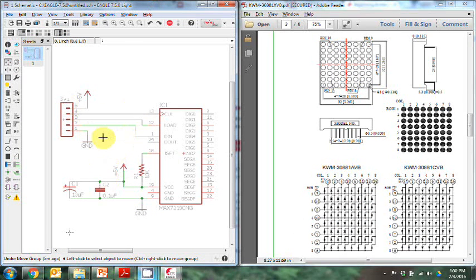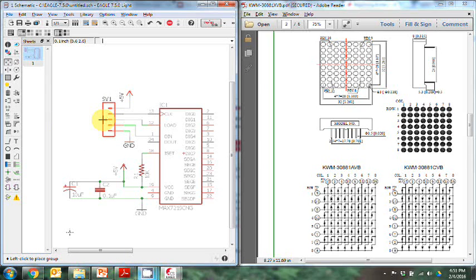So now that most of my schematic wiring is done, I want to do a little bit of cleanup, right? So what I'd really like to do is to move that header in a little bit. It's kind of sticking out. Now I can just move the component, but it doesn't move all the things connected to it. So I'm going to use the group tool to highlight a whole bunch of stuff. And you can see once I've selected it, the move tool is automatically selected. So I'm going to hold down Control, then right click, and I can move the whole group at once, which is really nice. So next we want to add the connections to the LED grid to all those over there.